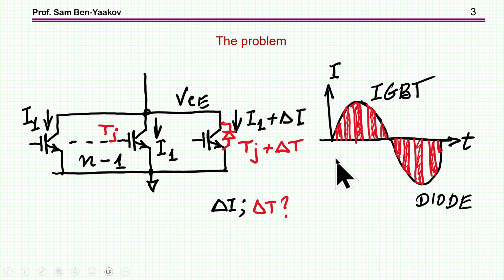The objective is really the understanding, and for that I'm assuming a constant voltage here. That's not realistic, but you might say I'm talking about the average voltage, due to the waveform of the current in practical cases. So we are talking about an average current, not about reverse current, which passes through diodes, not through the IGBT. This is why in such a case you're going to have an IGBT with the diode inside or outside in order to allow for the reverse current. So I'm not going to dwell on that, just to talk about the transistor itself.